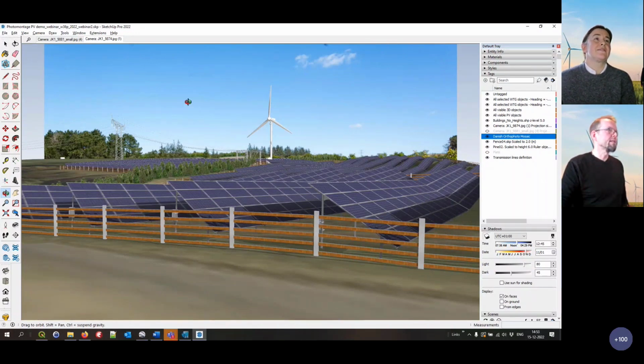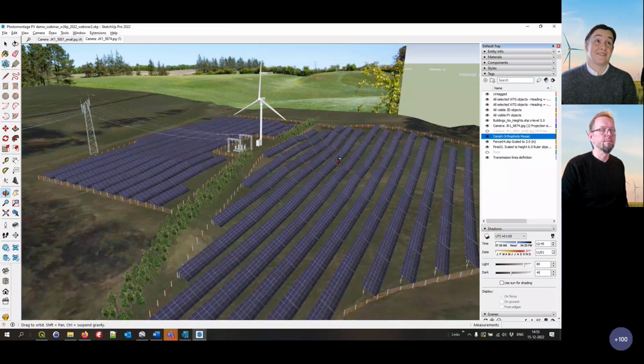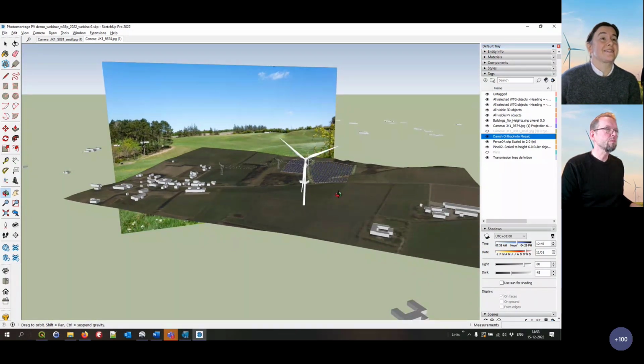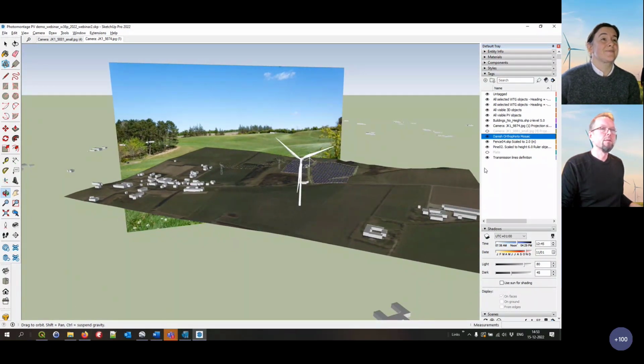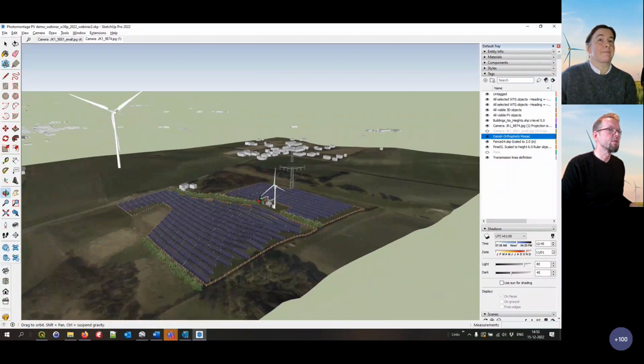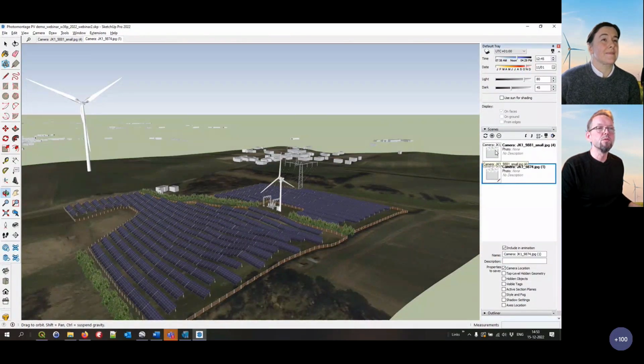I didn't show how to get your project from SketchUp into a website. So if I want to show it as a web link, then you can first define scenes, like these scenes I have here. And I could create several of those. Maybe I think that this is a very important position right here that I want to show the project from. Then I can create what is called scenes. We have 1 or 2 down here. That's the 2 photomontages. I create a new one.